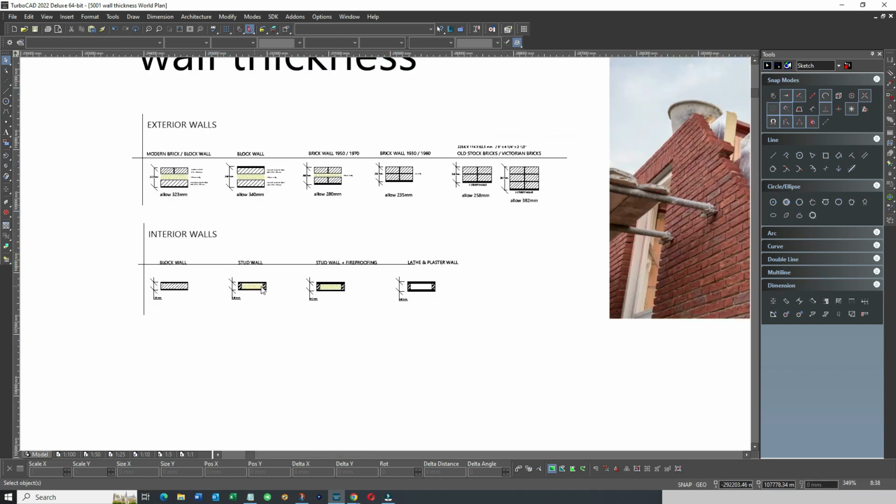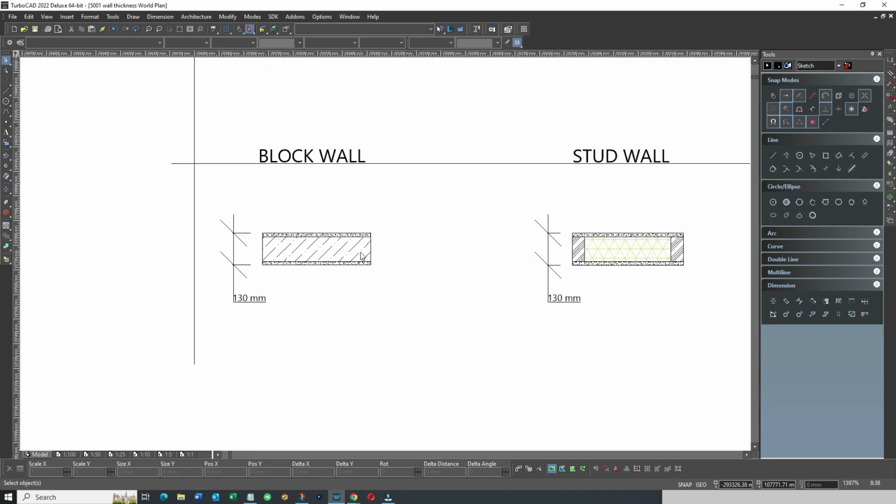Right, interior walls. Interior walls is another contentious issue. Now these are really important when we're doing conversions, because with wall thicknesses, as I say, you're sometimes struggling to fit a bathroom in, or a shower. If you're really cut for space, you're thinking, okay, can I get away with a stud wall? Maybe instead of 100 mil stud, maybe I can get away with 75. So you play with the numbers just to slim down the walls a bit. But what I'm going to give you here is kind of standard sizing.